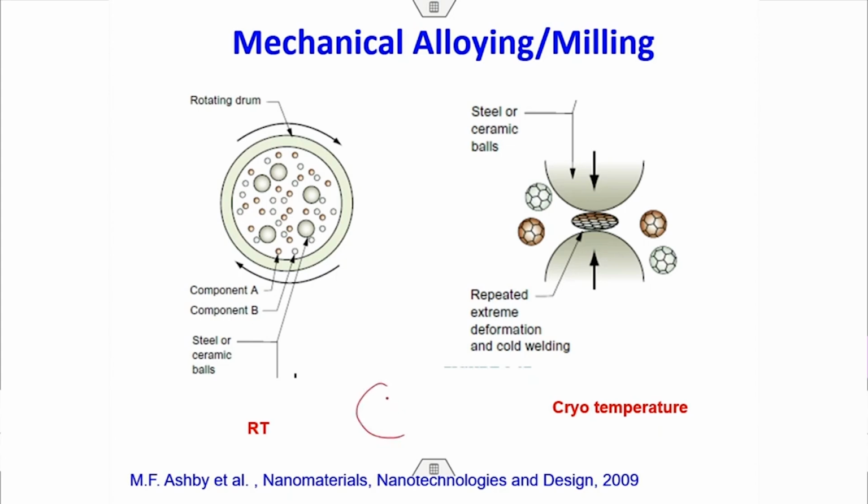You can generate a lot of defects inside the grains, and these defects slowly align. These defects, which are nothing but dislocations, can align and produce nanocrystal grains easily. You can align them and prepare nanocrystals, and these grains are actually small angle boundaries. Correct. So they then slowly become high angle boundaries.